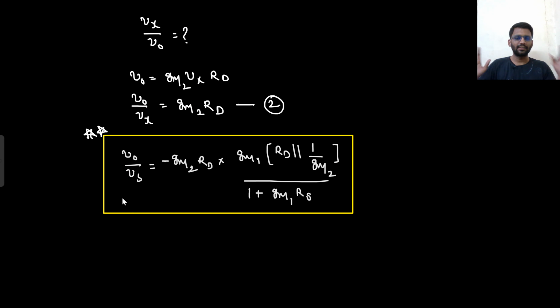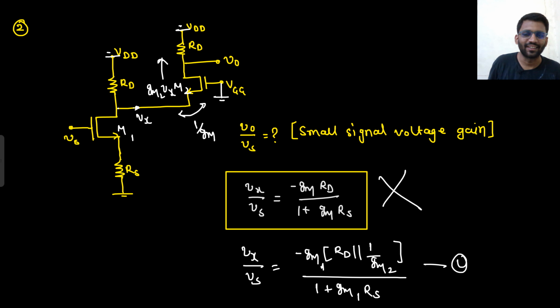Well and good. Everything is crystal clear to you. What you need to do is write the gain of the first stage, then write the gain of the second stage. In problem solving, what I will do is first write down what will be my Vx, so that I can solve the problem quickly.